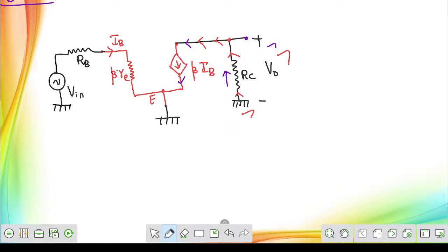Now, from the direction of the current, for a resistor, resistor is a passive element. From the basics of circuit theory, we know resistor is a passive element. So current entering point is plus, leaving point is minus for your resistor. Now the current will be traveling in the upward direction, sir. Whereas we are measuring the voltage in the opposite polarity. So first, in terms of current, this resistor is RC and the current that is entering into this branch is beta times of Ib. Then in terms of current, how will you write down the voltage drop, sir?